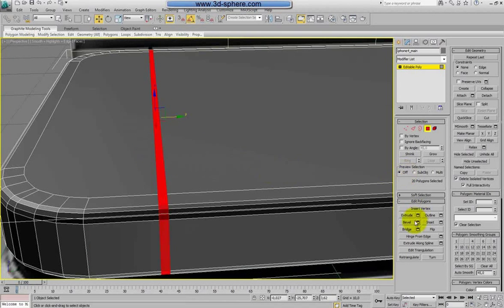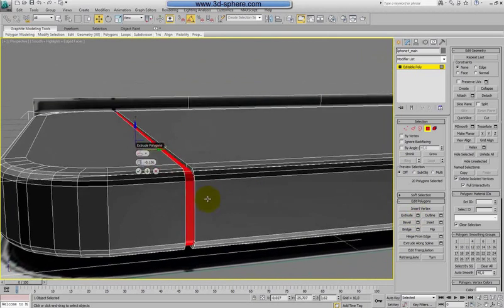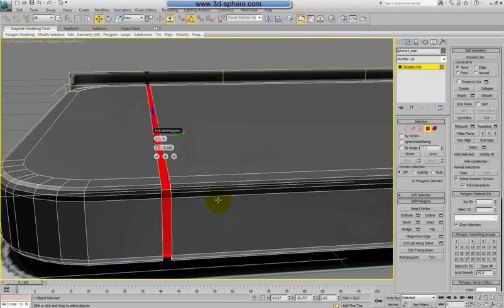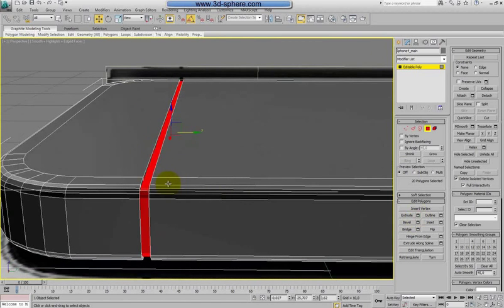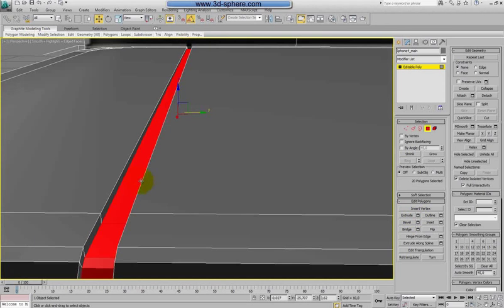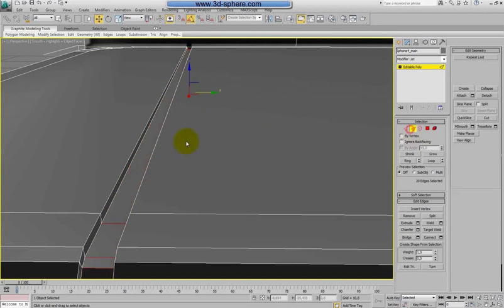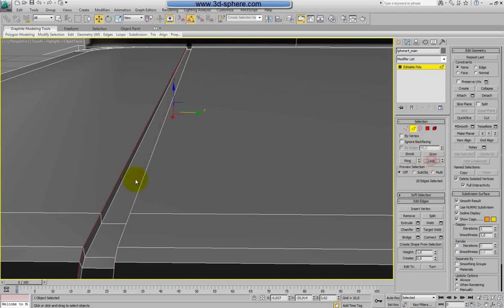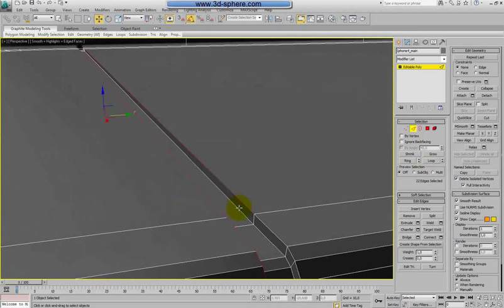Now we're going to extrude it inside. So we'll change from group to local normal and go inside like this. Press OK. Now we have to transfer the edges like before, also here. So I hope the loop function is working, which is very good.